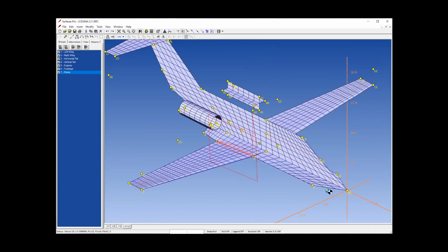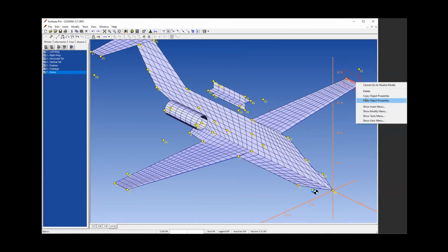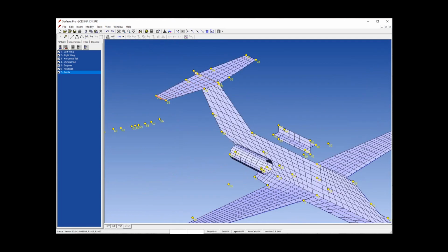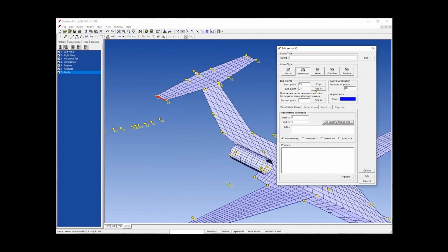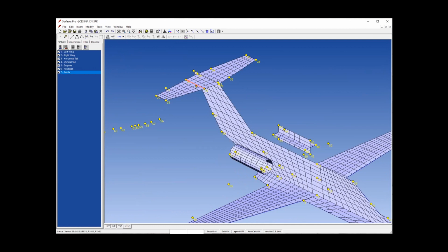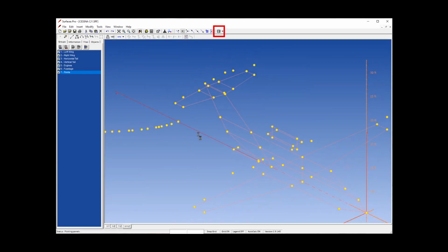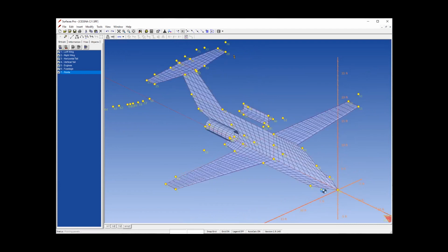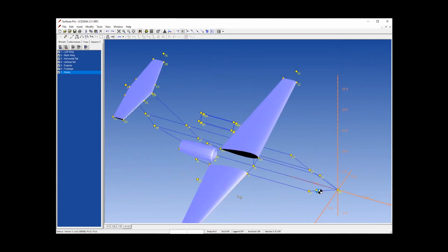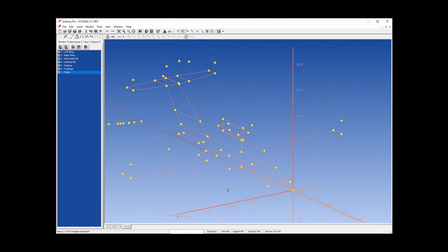Let's copy-paste this to the left wing. Then let's add airfoils to the horizontal, say NACA 0010 for all stations. Now we're ready. See this new icon? Press it to display the model with three-dimensional effects. You note that since the nacelle we added earlier also uses an airfoil, the effect extends to it.